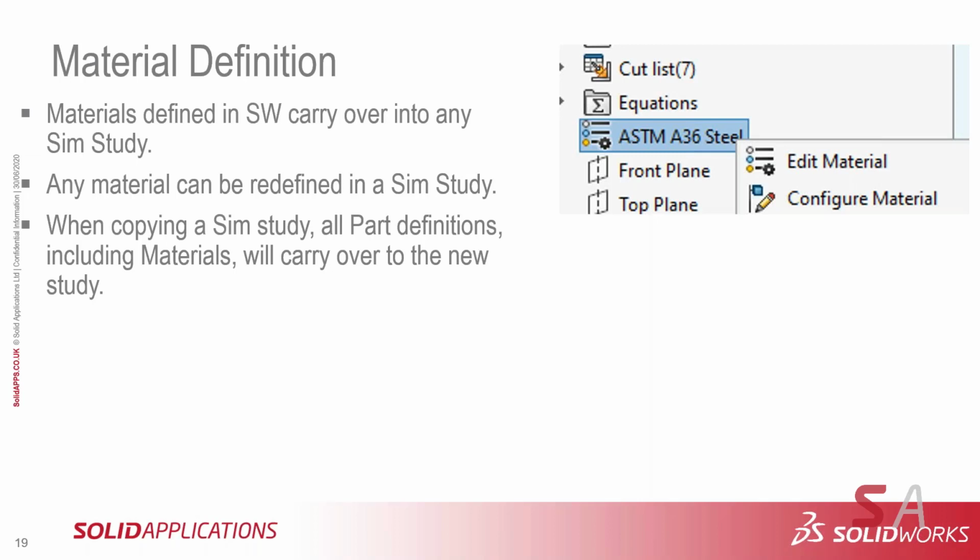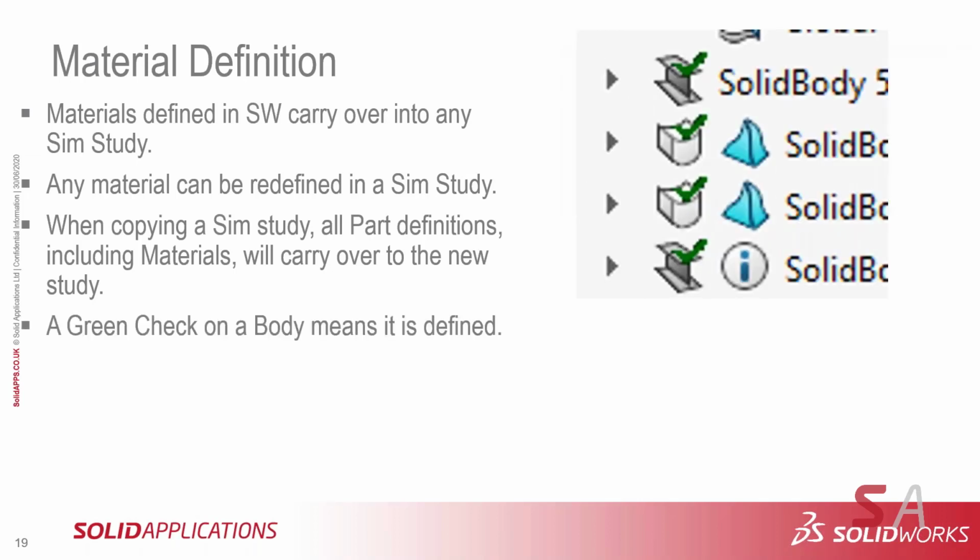So you might be running 3 studies with one thing as a sheet metal shell and another 3 studies, the same studies, as a solid, but you at least should get everything set up in each study that you're going to copy. It'll save you time.